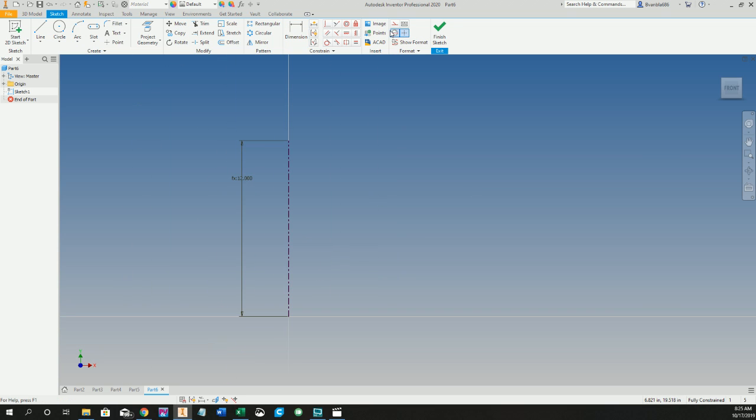Now let's start drawing our profile. I'm going to turn off the center line construction, pull off the end of the shaft, pull that up, and just kind of draw the profile. Right now we're not concerned about the dimensions. Now we can start throwing in some dimensions, and you can either type it in or you can list your parameters. I usually type things in if they're short. Again, this width could either be width or thickness, it does not matter. You can see the little circular symbol. It's going to be 3 inches.